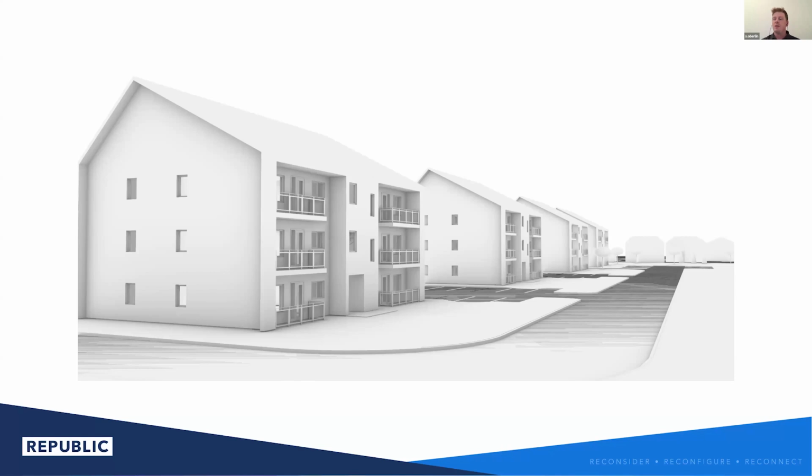I will note the effective values of the roof assembly are R86. It's about a R95 nominal. It's blown in cellulose. The exterior walls are effective R32. They're a nominal R46. They're a hybrid wall. So it's a 2x6 wood stud cavity plus 6 inches of through fastened exterior mineral fiber insulation. Our floors on grade also have an effective value of approximately R17 and a half with a nominal value of R20.